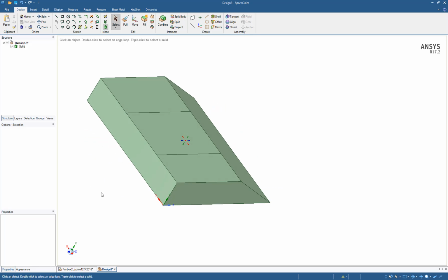If you remember from the earlier dimensions, this step in the middle was only about 4 inches down. We're going to move it a little bit lower this time. We're going to bring it down to about 5 inches. So let me select this. Actually, I'm going to select both of these faces.